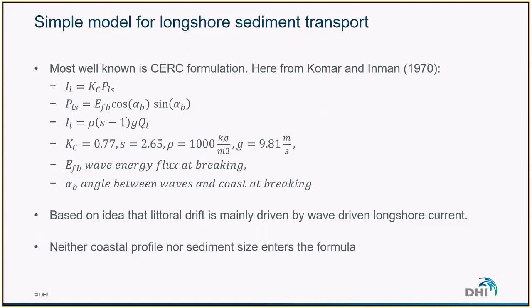So how do we calculate the longshore sediment transport rates? There are relatively simple formulas for calculating the longshore transport. One of the most known formulas is the CERC formulation. This formula relates the wave energy flux at the point of breaking with the littoral drift.